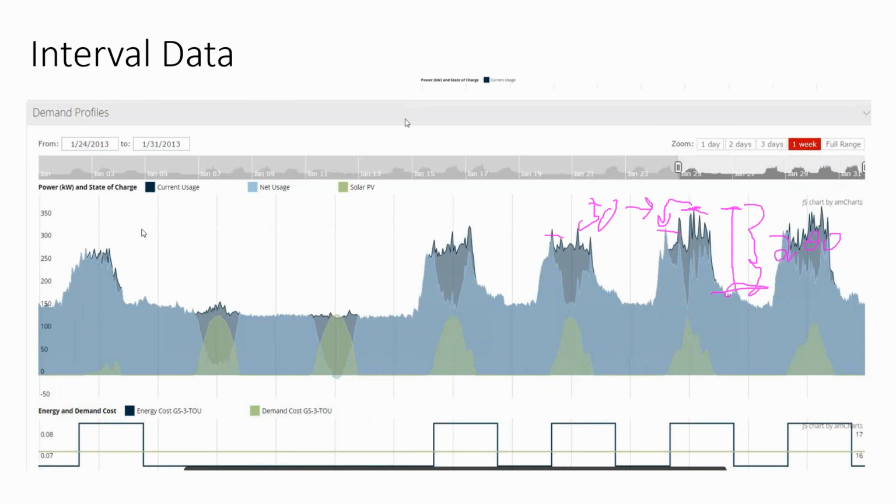And then again, the danger is if a cloud turns the solar array off, our peak could spike back up and we would have one 15-minute period where that one cloud in the sky turned the array off. So that's why historically we have not been able to model demand savings with solar, even though it is substantially reducing the building demand during the day, just not quite enough to overcome the limitation of that electric bill.